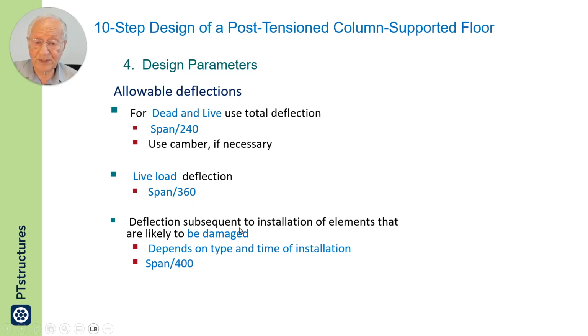For deflection subsequent to installation of elements that are likely to be damaged, brittle members, it is span over 400.